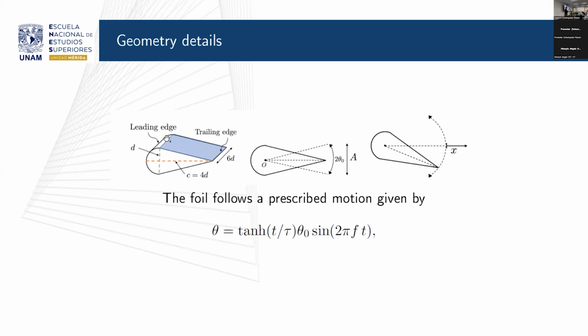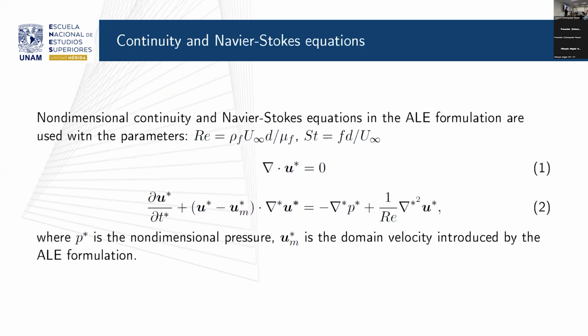This highlighted area is the one we use to non-dimensionalize the hydrodynamic forces, and the angle here is just to set this A parameter, which is the amplitude of the oscillation, to 2. So the angle is 0.28 radians. We have different aspect ratios and different chord lengths, but for these results, we chose just one. The chord is 4. These are the quantities that you can see.